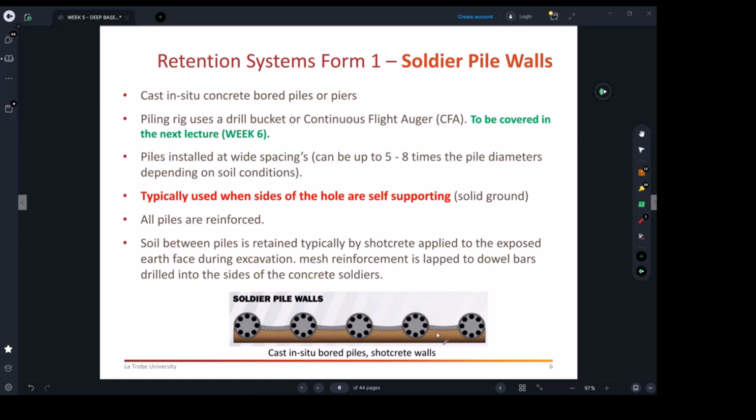Now, the thing is, from the time we build those up to the time, maybe it will take 2 weeks or so to build that. Is the soil able to bridge over itself from one pile to another? That's the question which will be answered by the soil engineer. They will give advice in terms of how far they need to be separated from each other. Right. And based on that, the structural engineers will be designing such walls, and that's what you're going to be building.